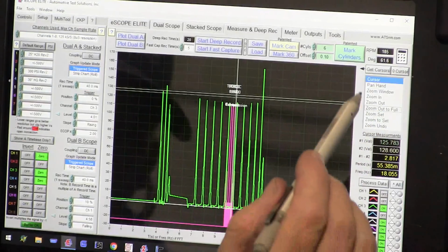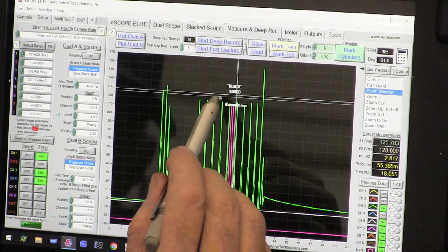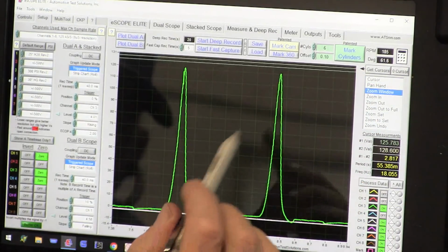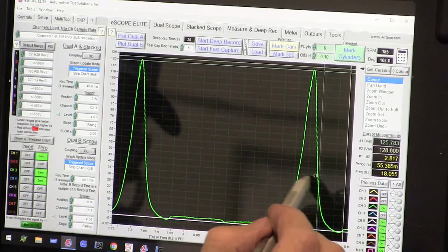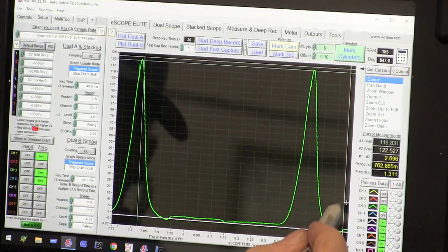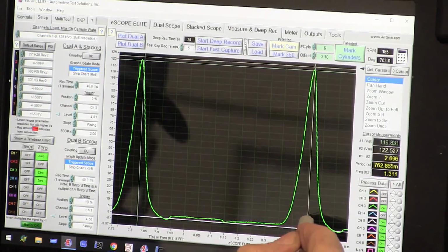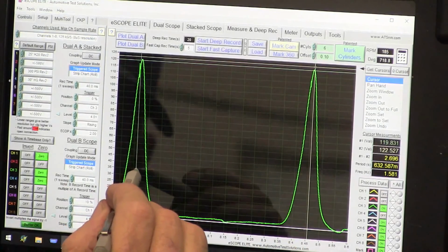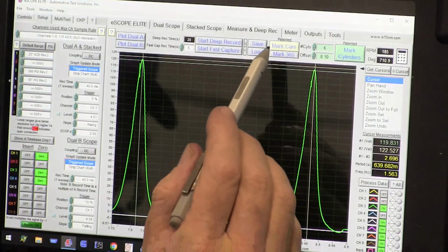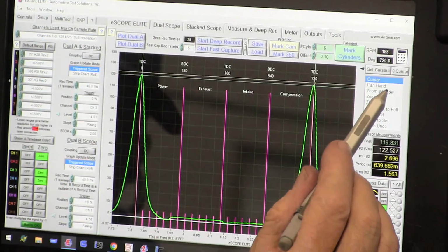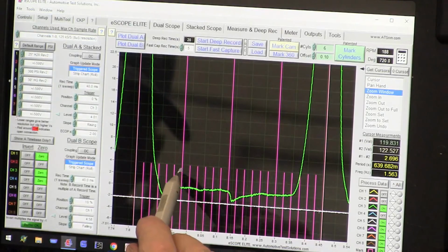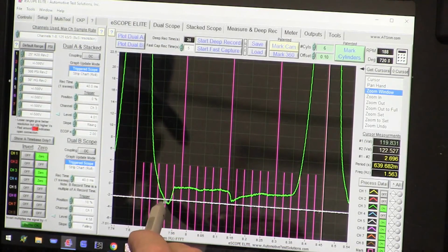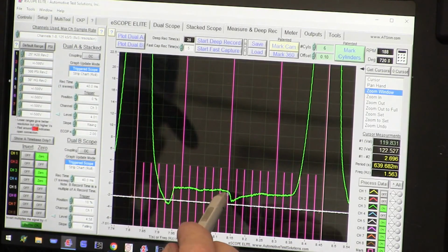And we always want to do what? We always want to look at a couple of waveforms. Never just look at one when you get them. We always want to look at a couple when we're doing pressure stuff. So we're going to mark each peak, mark cam. Then we're going to get our cursor or our zoom. So again, that's bottom dead center, 30, 60. I'm about 50 degrees there. I'm dropping about top dead center, which is what I expect.